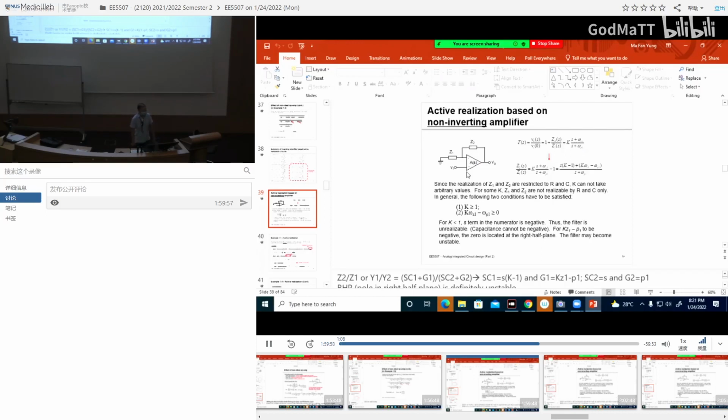Positive feedback means a small change in output will become added to the input. Output will increase, add back to the input, input will increase. Output increases some more, add back to the input. Everything will just saturate, max out. It will not stabilize. You don't believe, you go to the lab and hook up components.